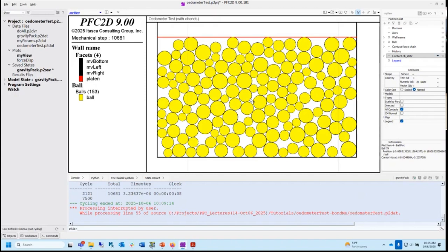And this is exactly what would happen in a sandstone. The sand gets compacted over many years at a certain pressure because of the depth. It has a certain amount of packing pressure, and then it undergoes a cementation process. But you might have other sandstone that's deeper down, at even higher pressure, and then it gets cemented. If the cementation process was the same, the one deeper down is going to be more well connected. It's going to have more cement, be stiffer, and be stronger, because we're actually diagenetically constructing the rock.